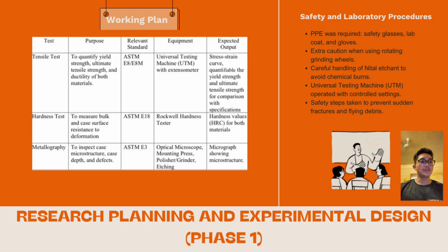And for the safety and laboratory procedure, PPE was required: safety glasses, lab coat and gloves. Careful handling of nital etchant to avoid chemical burns. Universal Testing Machine UTM operated with control settings. Safety steps taken to prevent sudden fractures and flying debris.